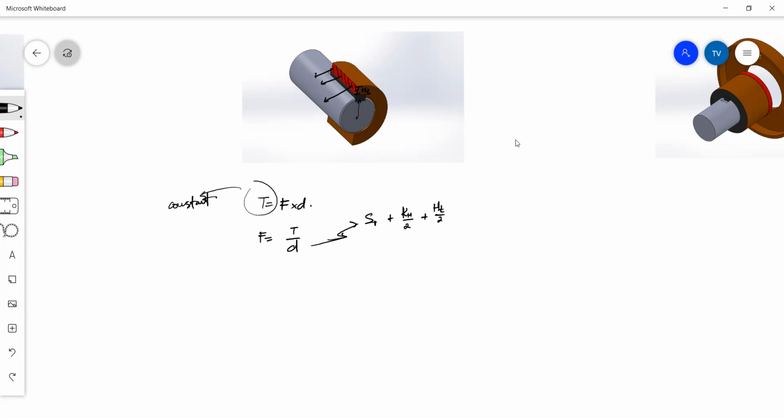So you can assume any hub thickness at this point, okay? So let's just say we assume hub thickness to be 18 millimeters for now. Using that, we would then calculate our tensile force. Since we're looking at tensile force, we'll look at tensile stress. Stress is equal to force upon area. The area is the area of this red zone.